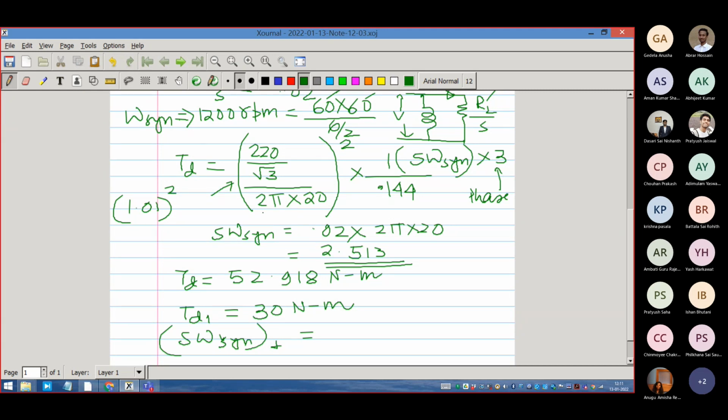And this part, V by omega sin, this red part, will never change even if you change omega sin, because you will correspondingly change the voltage. For this machine it represents the flux, in fact flux squared. So the flux never changes, and the changeable part is only this fellow.